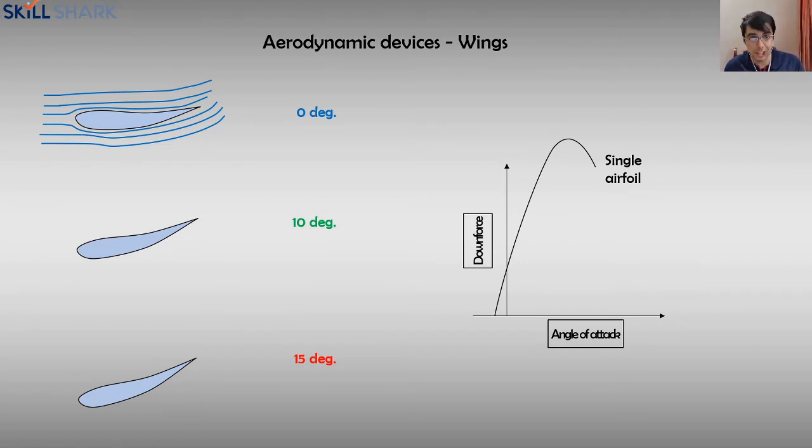So it adds an additional rotational element to the air, making it flow quicker. Now there are a lot of misconceptions and explanations where people say that particles will split at this point, and because this length is more, it has to travel quicker. There's no need for it to travel quicker. It's not granted that it's going to travel quicker, and it's not always going to meet at that point. Flow underneath just gets accelerated because of the Coanda effect.